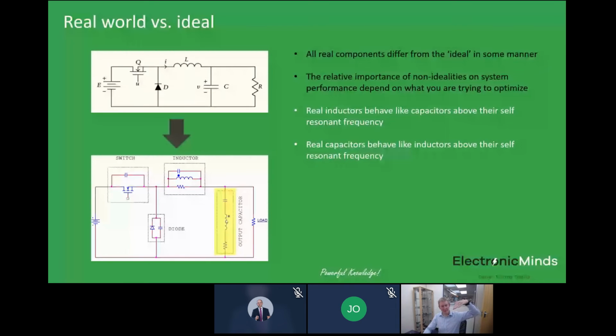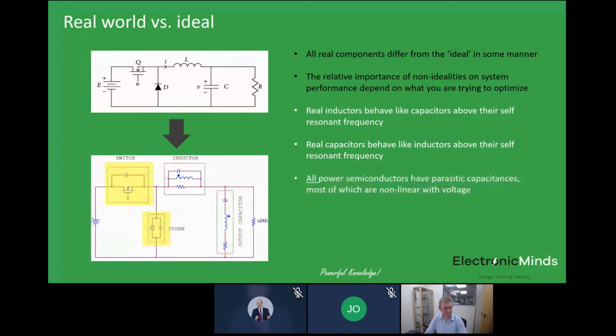The impedance goes down as we go up with frequency. And when we reach the self-resonant frequency of this capacitor, it starts to look inductive and the impedance starts coming up again. So if you operate this capacitor above its self-resonant frequency, it looks like an inductor and it can't filter noise anymore. So again, you have to know about the parasitic behaviors of these components to understand how they're going to perform at frequencies that you might not have used them at before.